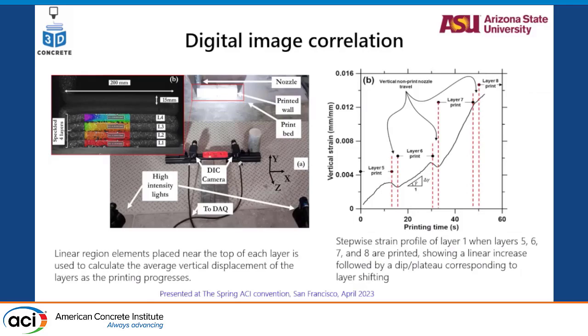So the previous part was the verification for the numbers, basically the failure height, but we had to verify that the model could predict the type of failure too, because how do you know if the height that we predicted for plastic failure is plastic failure and the buckling failure that we predicted is buckling failure? For that part we use DIC, so digital image correlation.